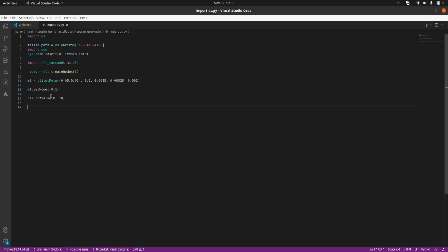And so here what I will do is empty dot set speed node and make it node number 2 as my speed node. So this node, you don't just assign it and it automatically notes that whatever value is coming onto this node, it's a motor speed.